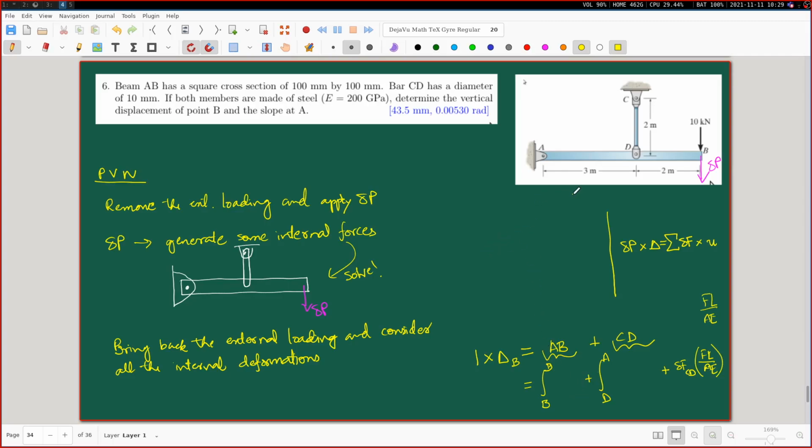where this kind of a structure is not going to be made of these linear elastic materials. For example, it is not made of steel, rather it is made of some kind of novel polymeric material. Then you simply cannot use Castigliano's theorem. You have to fall back on the principle of virtual work.